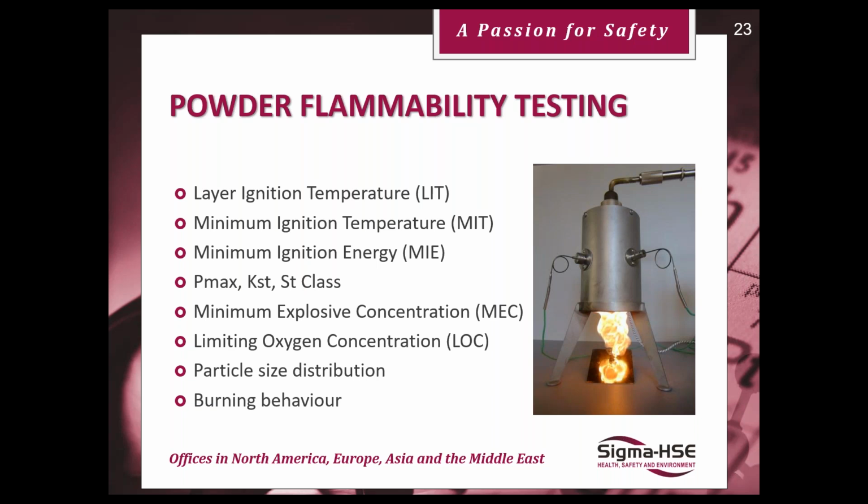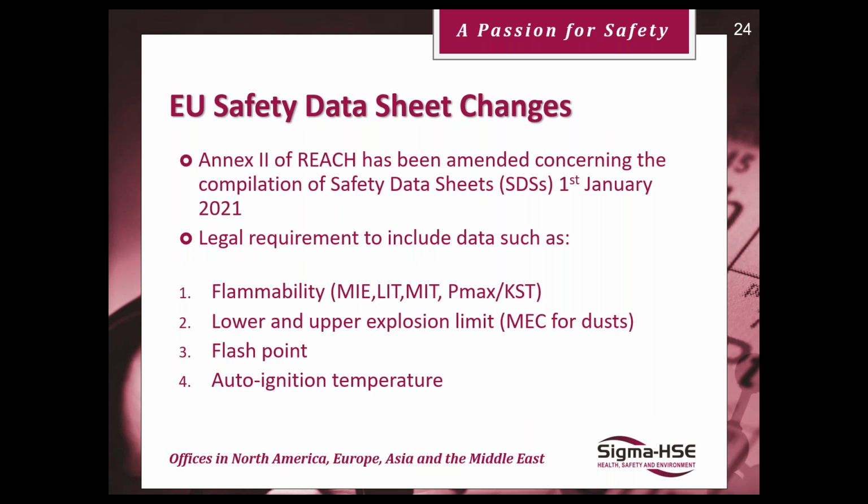And this has been picked up by the EU, and recently they have asked that safety data sheets include more of this data, especially when we're dealing with combustible dust. That the MSDS should contain things like minimum ignition energies, layer ignition temperatures, minimum ignition temperatures, Pmax, and so on,